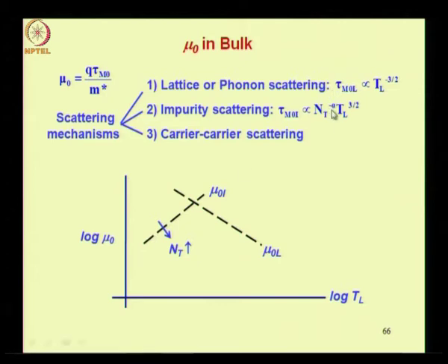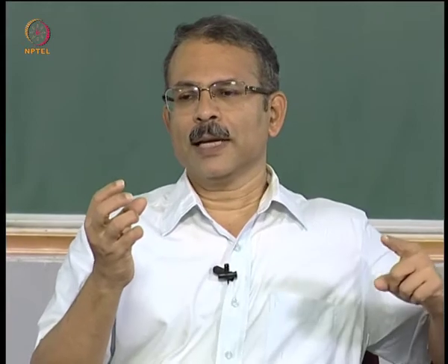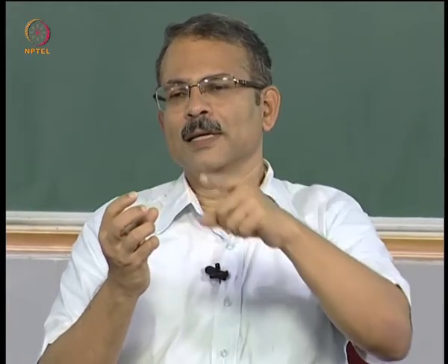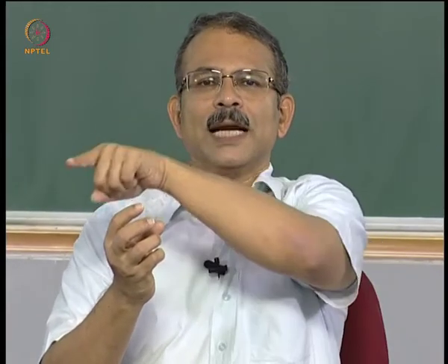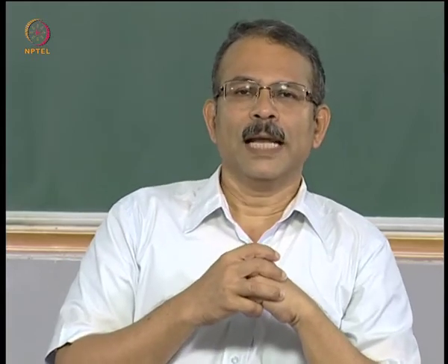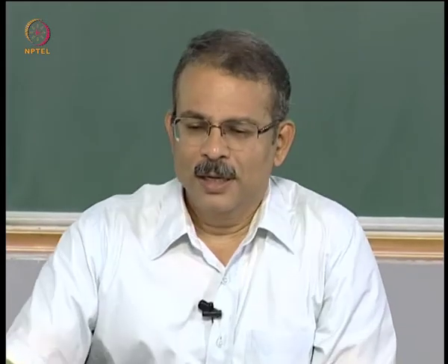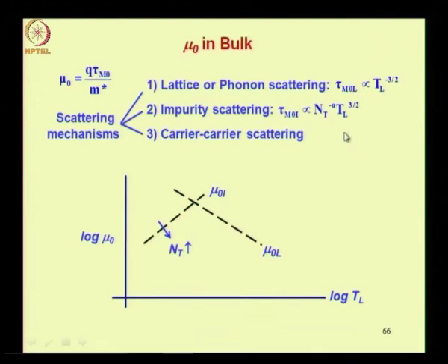that is why the negative power alpha. Further, we had also remarked that if the carrier moves very fast past the impurity atom, then the amount of scattering will be reduced. So you have an impurity atom and the carrier is moving very fast, then the amount by which the carrier will get scattered would be less, and therefore since the thermal velocity increases with lattice temperature, the amount of scattering decreases as lattice temperature increases for ionized impurity scattering.